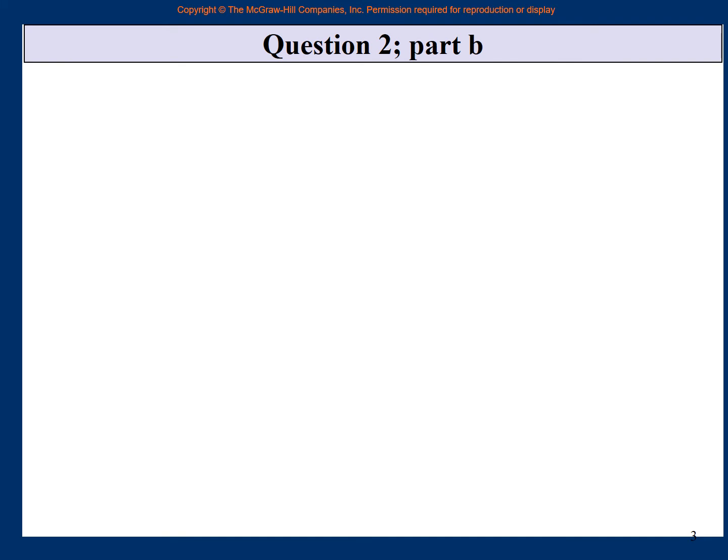Let us go to part B, where we were finding the die pressure at the exit and so on. So for die pressure, we have YF minus sigma D. And sigma D or sigma is the same, the pressure at the die, right? So call it sigma D, whatever. And YF, remember in the previous page, in the formula, it was Y bar, right? So there we used Y bar. This is simple Y, Y or YF. If you write Y, it is flow stress. If you write YF, it is flow stress. If you write Y bar, then it is the average.